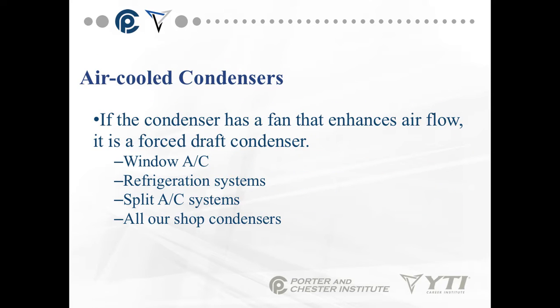If the condenser has a fan that enhances airflow, it is a forced draft condenser. Okay, window air conditioners, refrigeration systems, split systems, that's where your outside unit has your condenser and your inside unit is connected by a line set. And all of our shop condensers that are found in the shop equipment are air-cooled condensers.